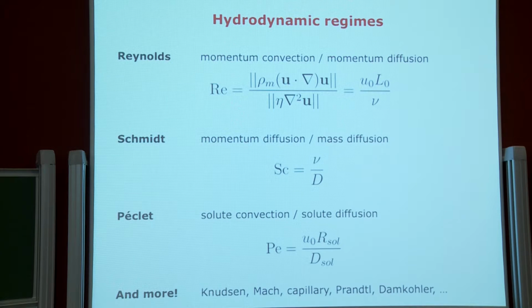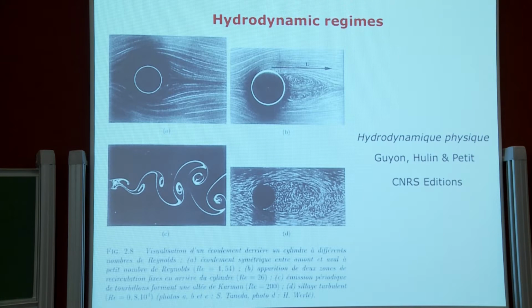So coming back to the Reynolds number, if you have a very small Reynolds number, you will have a flow that is dominated by viscous effects. And what you see here are experiments for flow patterns around a cylinder. So you see here from the side a cylinder, and you have a flow going from left to right. And the flow is visible here because you have a dye inside your liquid. And for very small Reynolds number, you have something that is called the laminar flow, with layers of fluid that do not mix, essentially, and that simply go around the obstacle.